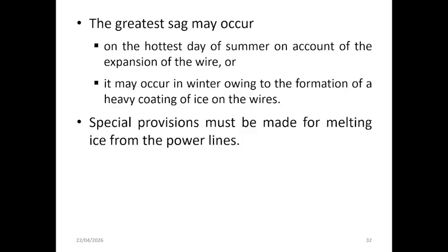Okay. This slide also explains the conditions under which the maximum sag in an overhead conductor may occur, emphasizing the impact of seasonal variations. The greatest sag is not limited to a single condition. It may occur during the hottest days of summer due to thermal expansion of the conductor.